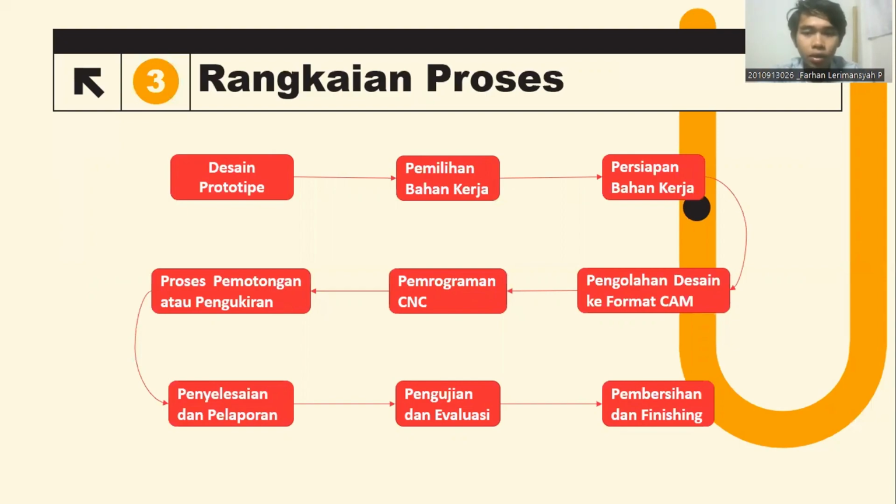Common materials used in subtractive rapid prototyping include metals such as aluminum, steel, or copper, or plastics such as acrylic or Delrin. 3. Workpiece preparation. Cut or shape the workpiece material to match the required dimensions for the prototype. This may involve cutting metal blocks or plastic sheets into shapes closer to the final design.